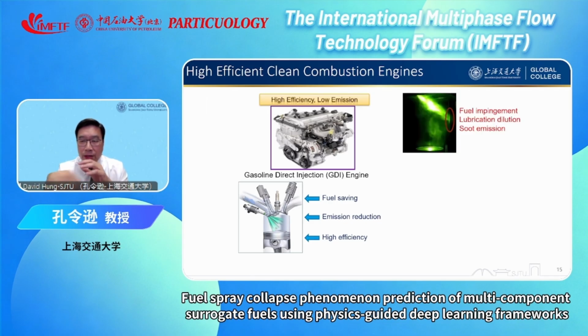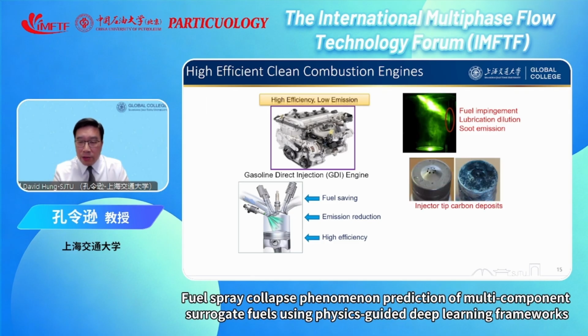However, things happen in the engine. One special issue is when the fuel is not mixed well and impinges on the cylinder wall. That is definitely a challenge, because the impingement causes a lot of unburned fuel that ultimately becomes soot. That is one problem. Second, you might feel that the fuel spray is simply injected through the injector into the cylinder. Well, yes, you're right.